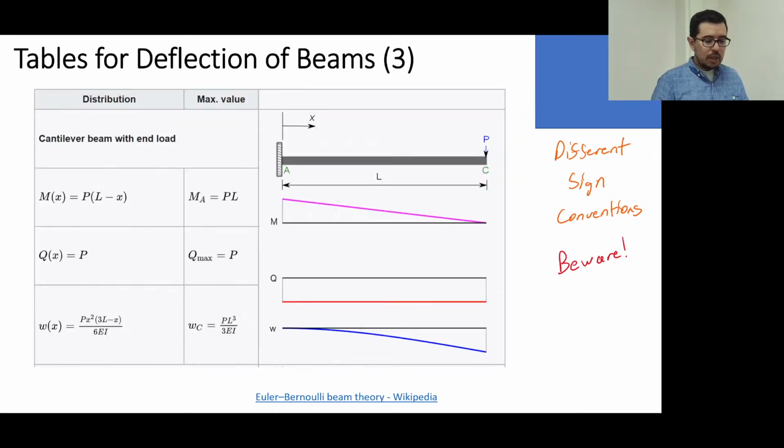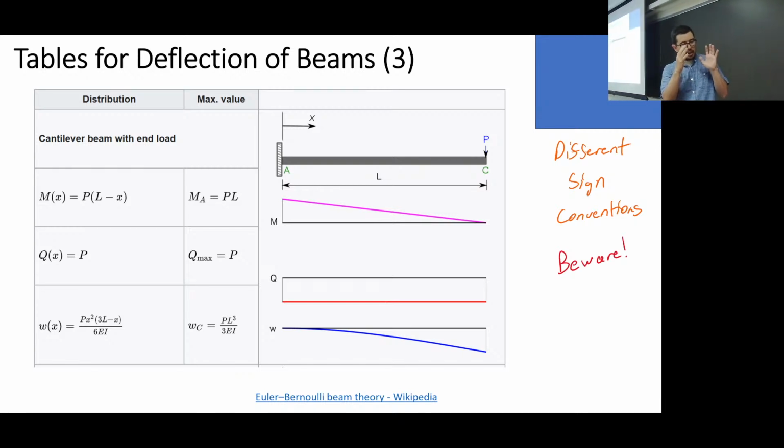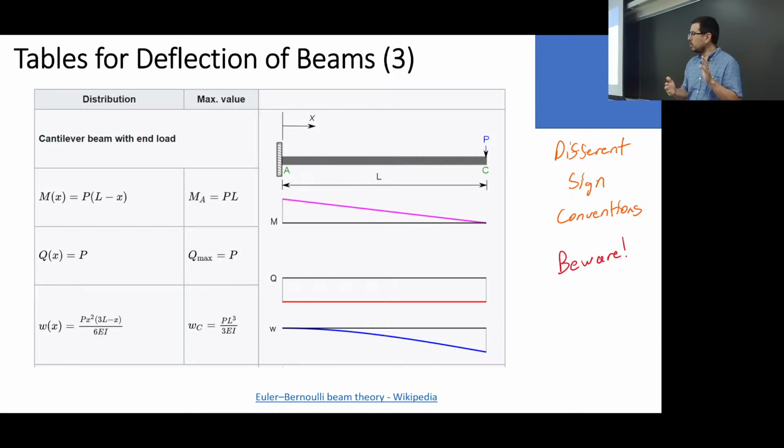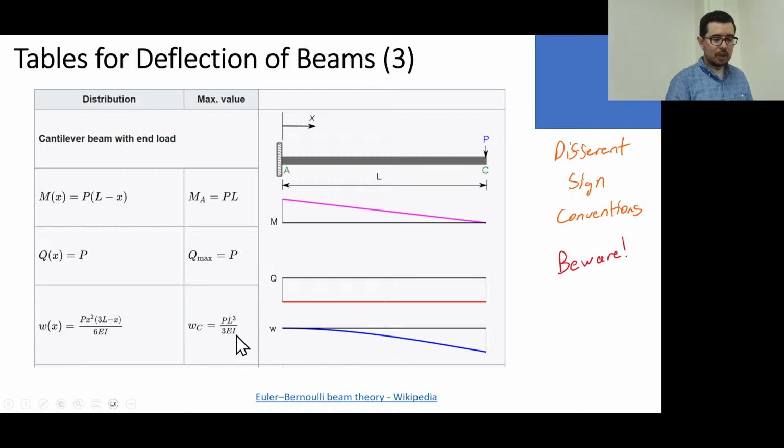So for example, if you were given, hey, I've measured the displacement at the end of this beam. This is a cantilever beam where a force is being applied to it. I measure the displacement there, and I tell you it's made out of steel, right? And I go and I measure the cross section, and I got bh cubed over 12. It's a rectangular cross section, so I've got I, right? So if I know the displacement, I know E, I, and L, I also know the length. Then I can figure out the P.